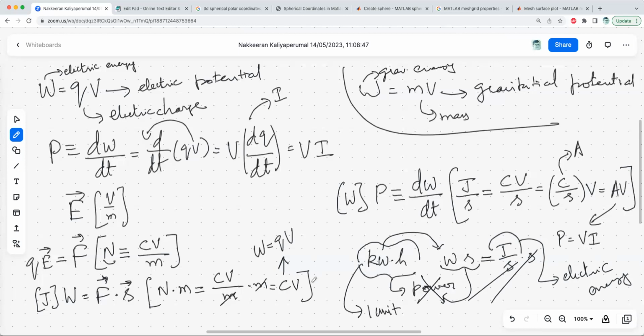In our electrical supply, power is supplied to our domestic or industrial users. They don't care how intensely you are using it. Sometimes you may have switched on your refrigerator, washing machine, aircon and everything, consuming so much power. They don't care. They care about how many kilowatts you consume in 1 hour. If you have a component like a microwave oven running at 1,000 watts, that means 1 kilowatt, and you use it continuously for 1 hour, it has taken an electrical energy of 1 kilowatt hour.